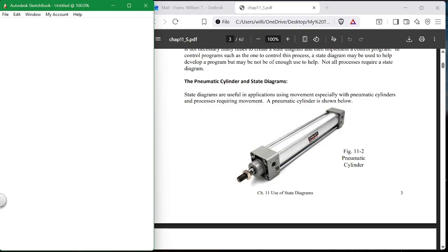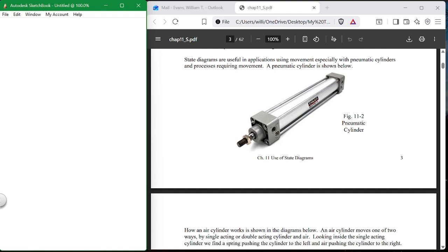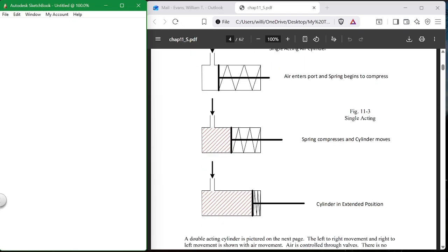We talked about before that if you are writing programs and you want to know whether there is a seal or memory circuit involved, you can ask, is there a switch that I need that I don't have? In other words, I need a 2-position switch or a 3-position switch, but physically there's nothing available that I can use for that. In those situations, that's a tip-off that you probably will use a memory circuit. And here, when you see these guys, it's probably a state diagram. Okay?